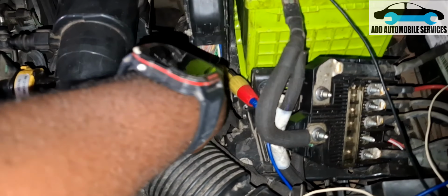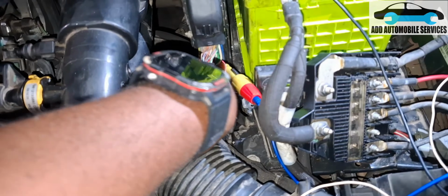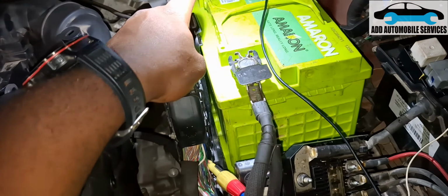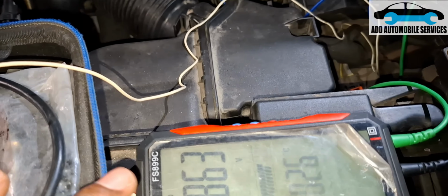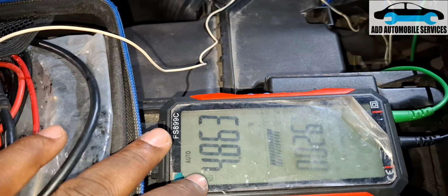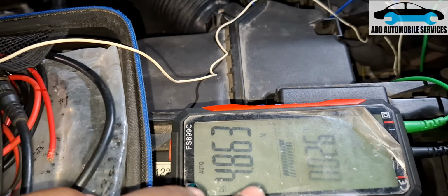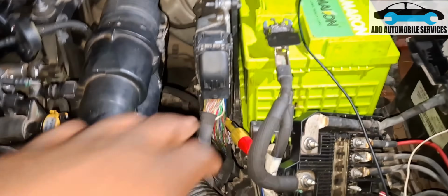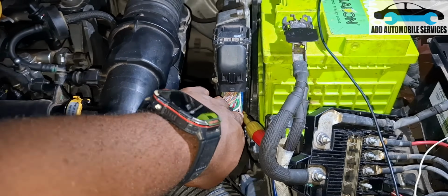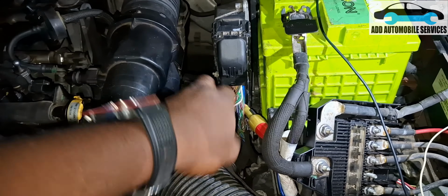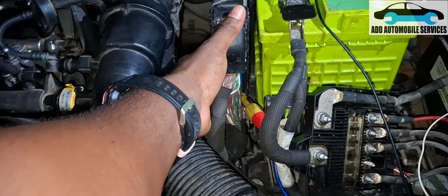So after the diagnosis, now we find out that the wire is connected to this side, and instead of the control board feeding it with ground, we've connected ground on our multimeter to check if the control board is able to feed it with ground. You can see we are getting voltage instead of ground. So that tells us that the control board is not able to bring the ground that the sensor needs.